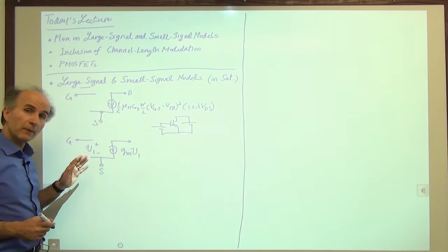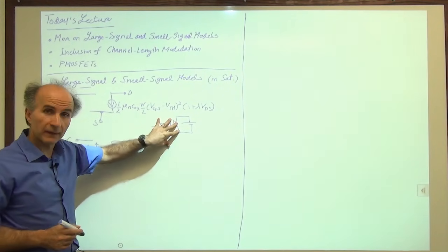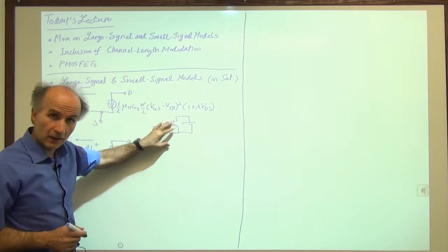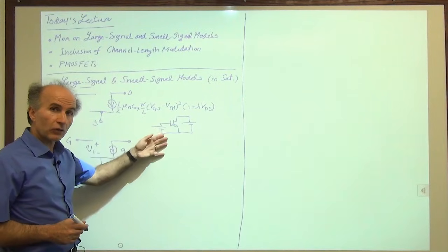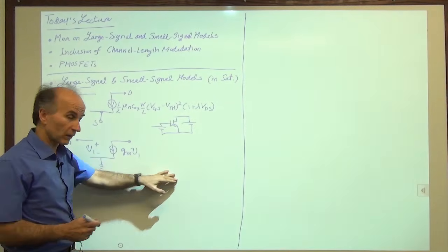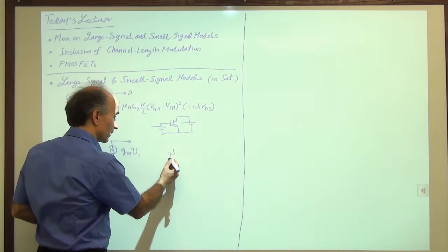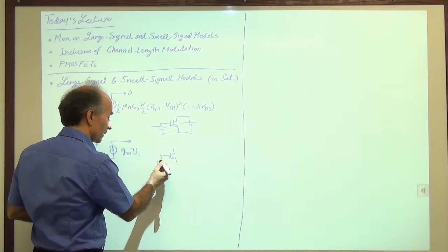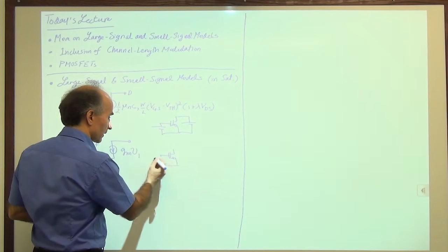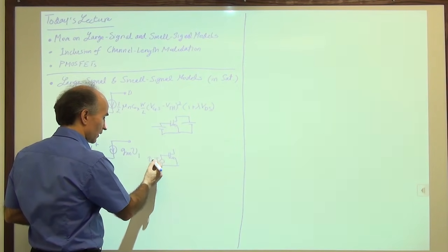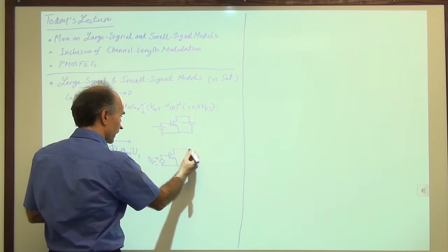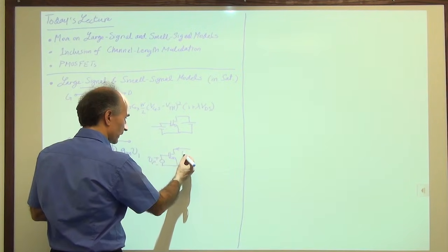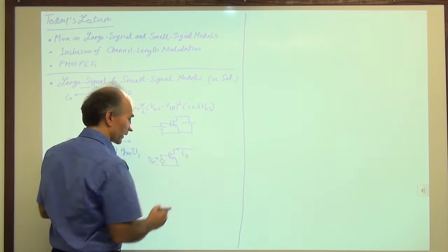Now that we have gm, we say, okay, if in the circuit a signal comes in, for example, applied between these two points, then I make a representation for only the signal. And that representation is like this. Let's call the signal v in, lowercase, to indicate it's a small signal. And then, for example, I'm interested in this current, id, also lowercase.